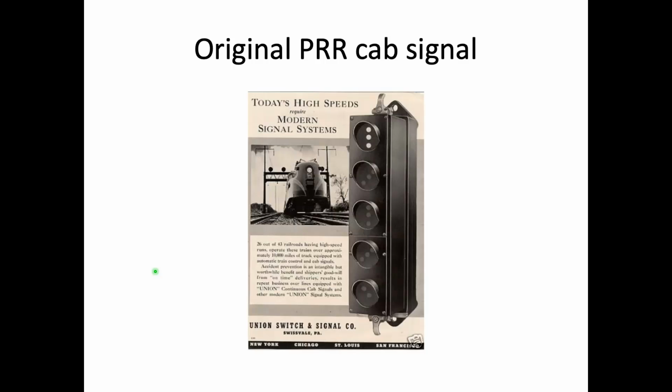Without the cab signals, you'd have to grope your way through the fog at a speed that would permit you to stop before hitting anything. In these conditions, without the cab signals, it would mean creeping at little more than walking speed through the entire 2 miles or so length of the block to the next wayside signal. But voila, the local crew snaps to attention and locks the switch back, and your cab signal indication changes to clear. Now, after moving only the length of your train, you can resume maximum authorized speed.